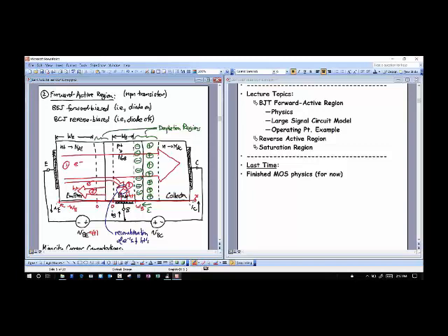And I will even say, because later on you'll see this, in general that voltage is going to be right around 0.7 volts. That's a good thing to understand right now, and we'll understand it even more. It actually isn't 0.7 volts, it's 0.689457 volts. To me, that's 0.7 volts. If you want a good grade in this class, it's 0.7 volts to you as well. The reason I keep saying that is that you don't want to keep worrying about exactitudes. You want to make approximations where necessary to get your answer much more quickly.